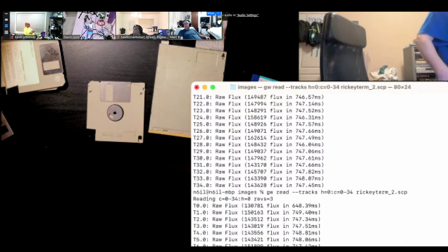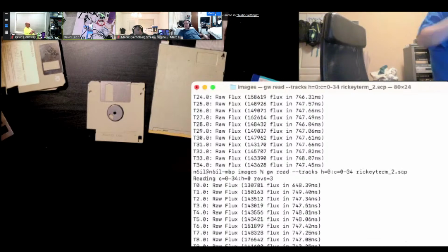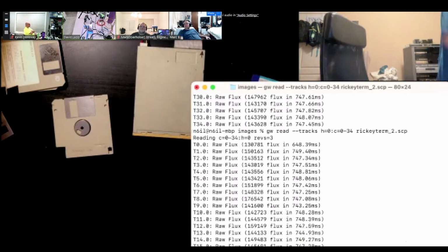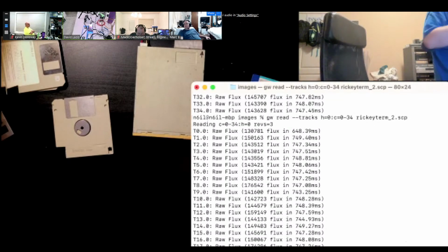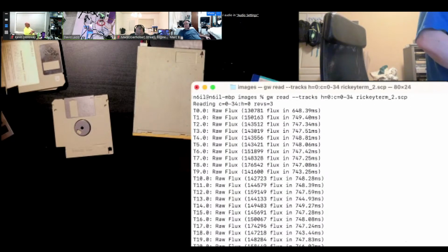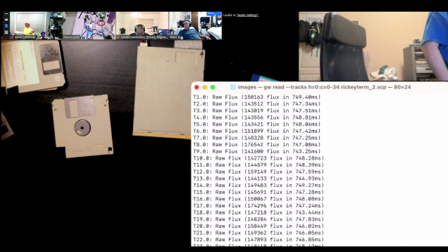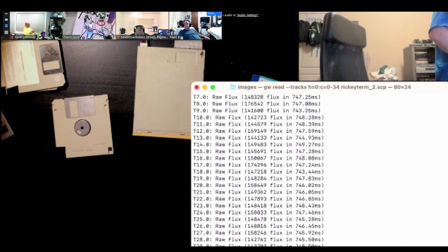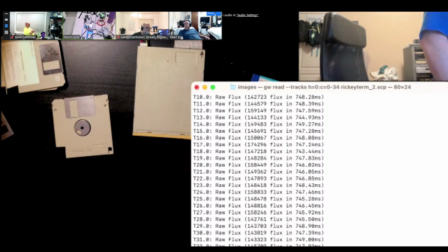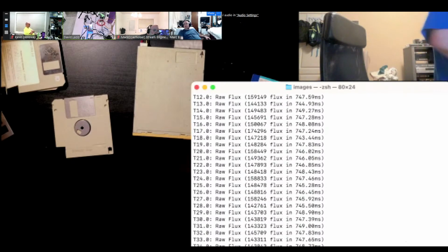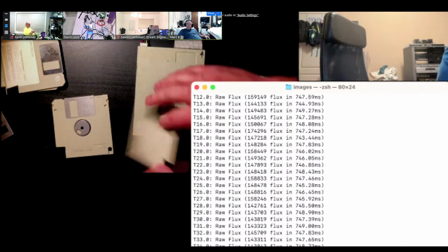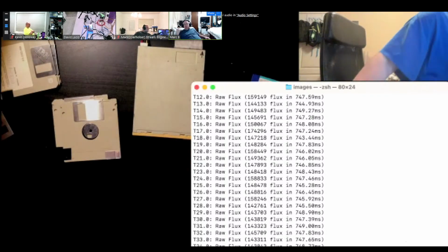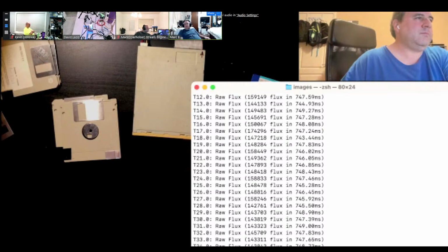I've been wanting to build an imaging station where I have all the different kinds of 5.25 on one thing, and one 3.5 to cover the 3.5-inch discs. Well, that's how I use the 1.2 meg 5-inch disc on the CoCo. I strap it to 300 RPM, so it becomes a 720.